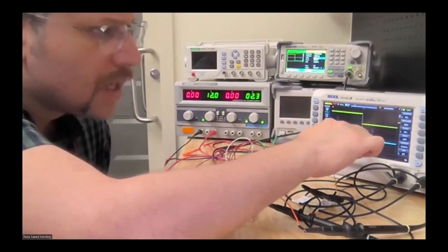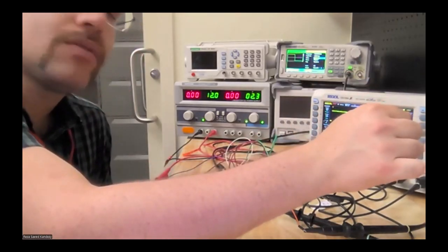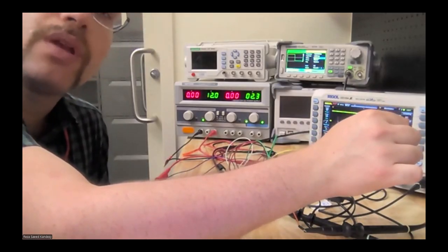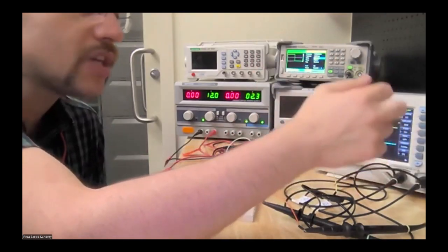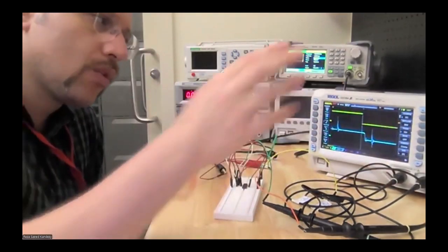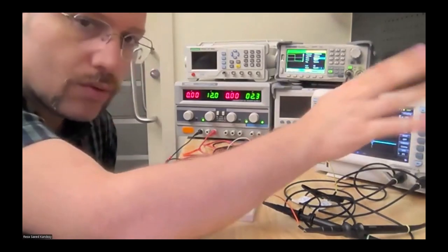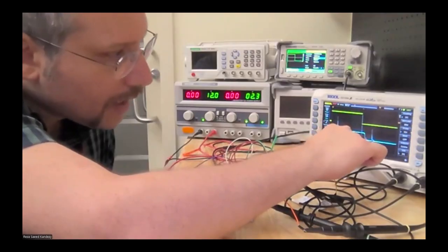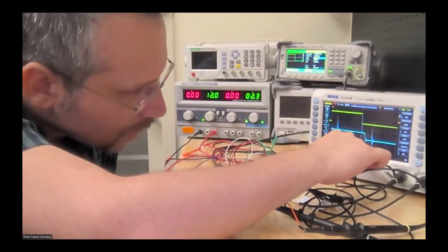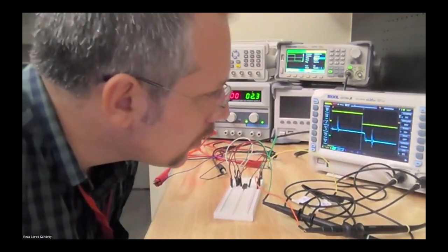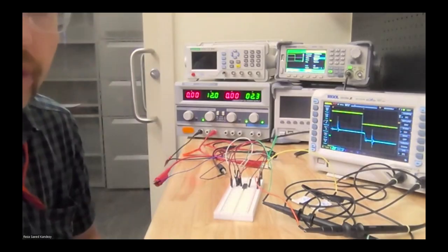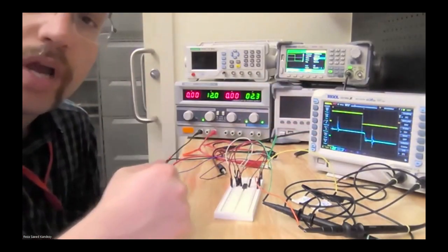And did I calculate it? The first one, I think I used 200 millivolts in my calculation for the rising edge. So forget about my error. You do the right thing and do your measurement. So this is 300 millivolts, and the falling time is 60% of 1 unit, which is still 5 microseconds.